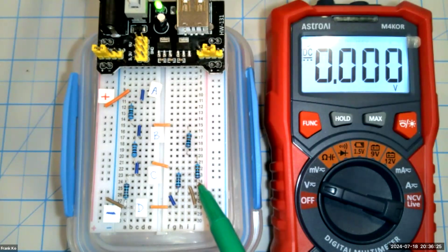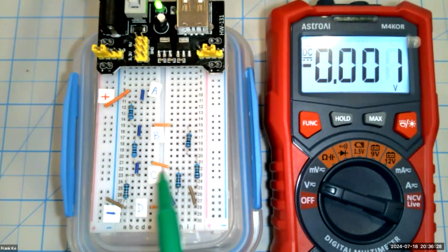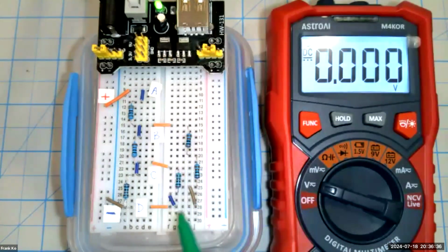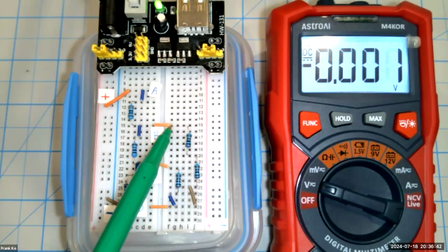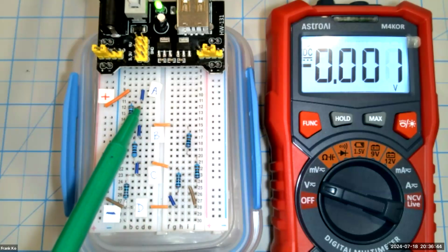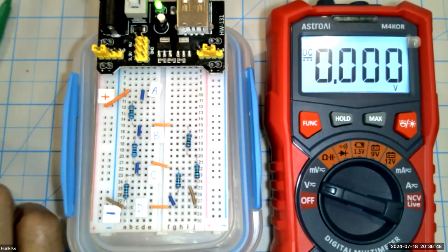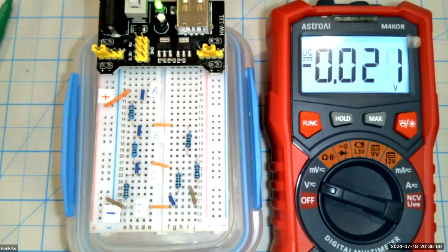We calculated 4K ohms to make that happen. 2 volts at point C, top of the load. We must have 1 milliamp of current. We calculated an R4 of 2K ohms. And in order to achieve 2 volts here and 4 volts here, we needed to restructure the ohms of R1 and R2. So now let's go ahead and check to see if our currents make sense.